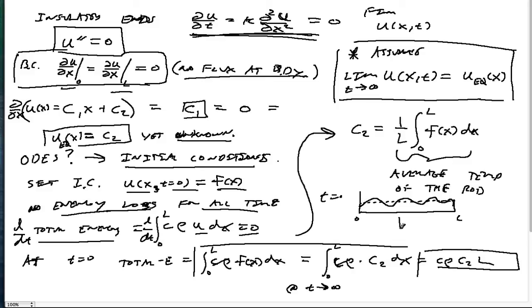All right, and so as time goes forward, and it heads towards infinity, we go from 0 to L. The end temperature will just be the same as the average, but all of the high points and all the low temperatures will get smoothed out and eventually converge towards the average temperature. So this is an important concept in understanding how the heat equation is working.